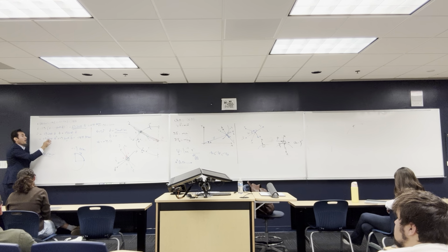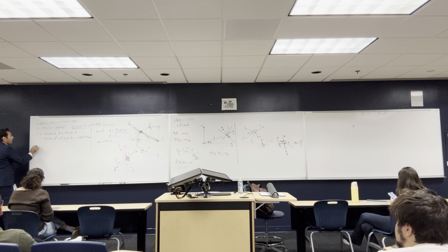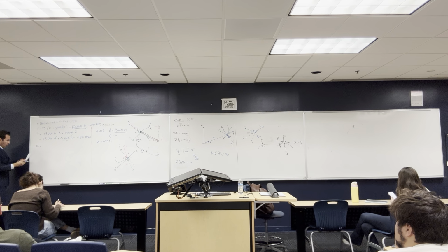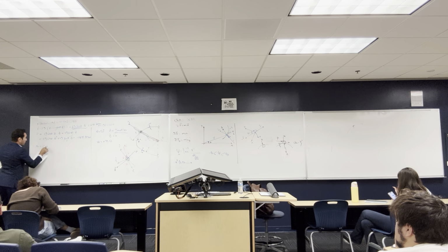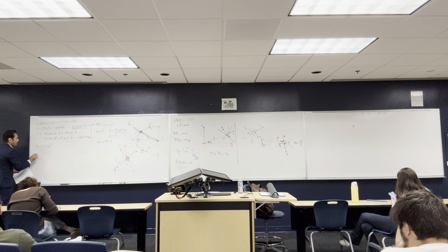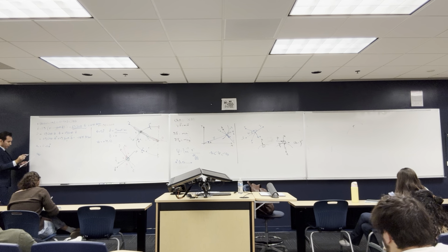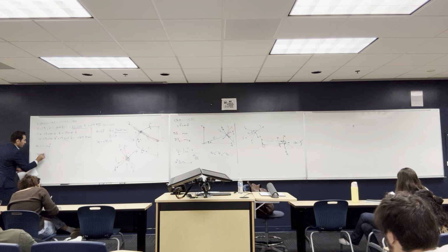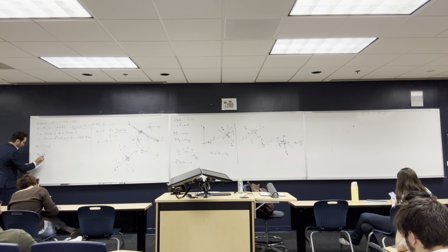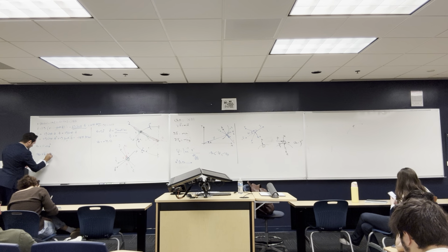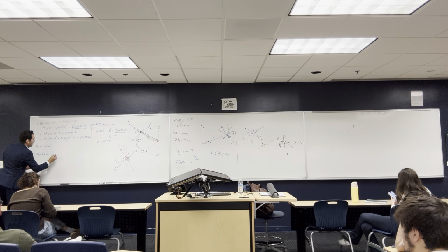All right, okay, so right now I'm ready to calculate A_R and A_theta. If you go back to your equations, you'll find that A_R is equal to R double dot minus R theta dot squared. That's back in the kinematics. And A_theta is equal to R theta double dot plus 2 R dot theta dot.